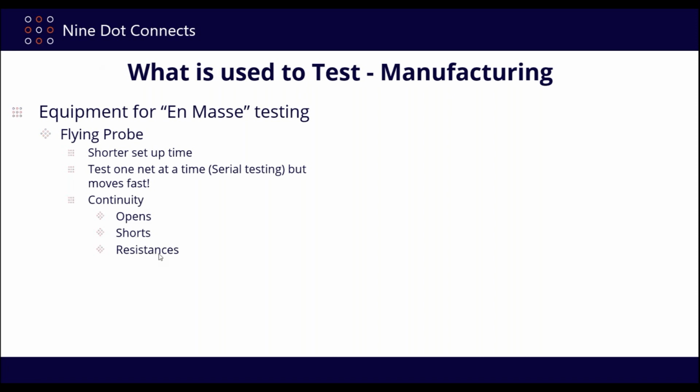So they may have had a point A to point B piece of wire, but the problem is that that particular copper may have been overly etched. And so it'll have a higher resistance because there's obviously less of a width for it to travel through. And so that can be an indication that the board itself, even though it does have conductivity, may not have the strength, or it may have a reliability problem. So that's what they would primarily do with this. So let's take a look at this over here.